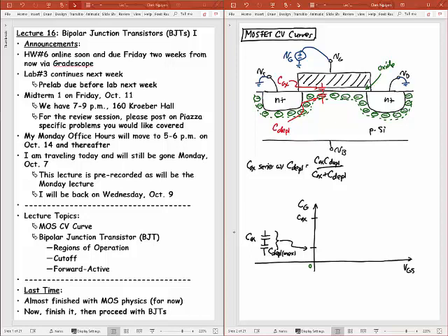They combine like a parallel combination of resistors would. And so in this case, right, if this is C depletion down here, the maximum C depletion, I guess that's not the maximum, it's the minimum C depletion, because that's when this thing has the largest depletion width here. That's right, I should call it the minimum C depletion, so I was saying it wrong before. Then any other C depletion here is going to be greater than that C depletion. So you get a series combination of a capacitance of Cox plus some C depletion capacitance that's greater than the minimum C depletion. And so that means the capacitance I'm going to get is going to be somewhere around here.